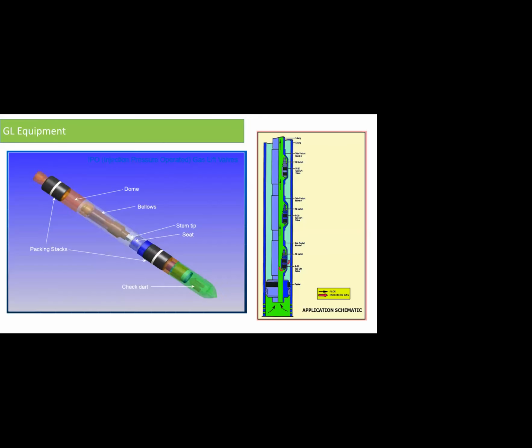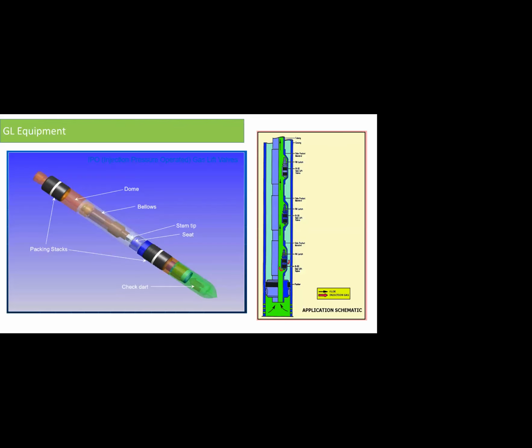So now we finished the concept of the gas lift and we understand it, okay? Then we will go quickly into the equipment. We all saw in the video that we have this schematic, we have this tubing and we have this increase in the size of the tubing, which is called the gas lift mandrel. The purpose of this increase is to put certain valves here. Through these valves, gas is injected, as we saw in the video, the gas is injected here, and it goes down here, mixing with the fluid coming from this side.